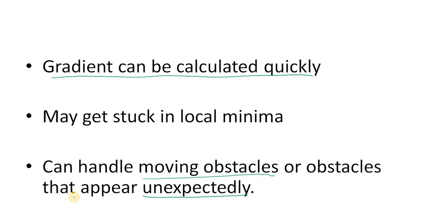So these kinds of algorithms, for example the artificial potential field, because they are very reactive and very fast, can do this obstacle avoidance and path planning in real time. They can handle these sudden changes in your model and also in your environment. But if you see the A-star algorithm, which uses a fixed map, this type of algorithm will fail in this kind of situation where the environment changes or where there are moving obstacles.